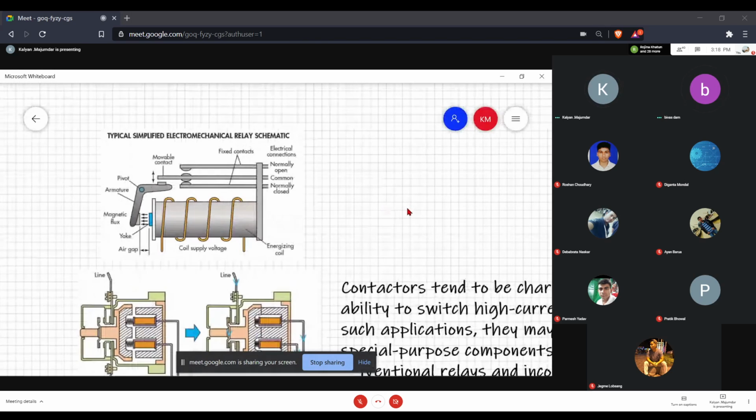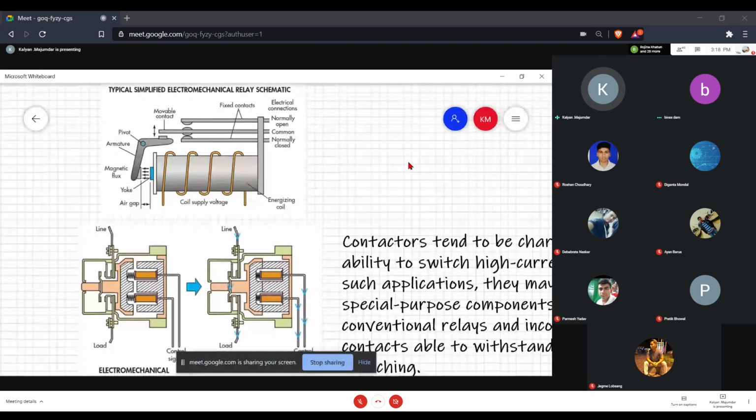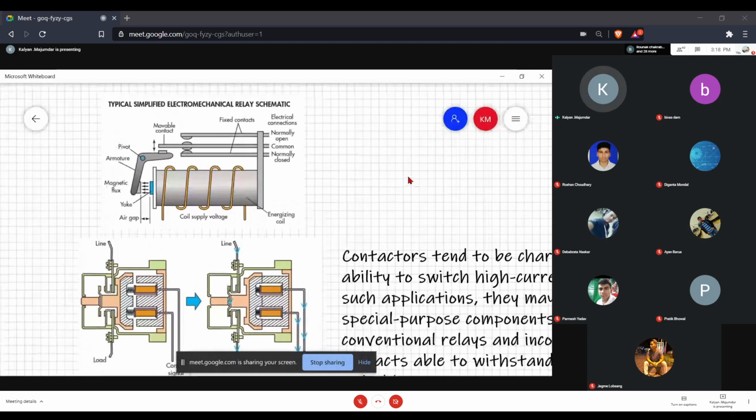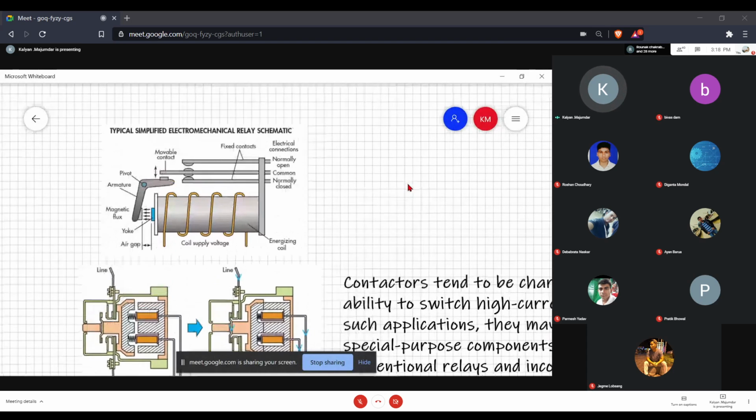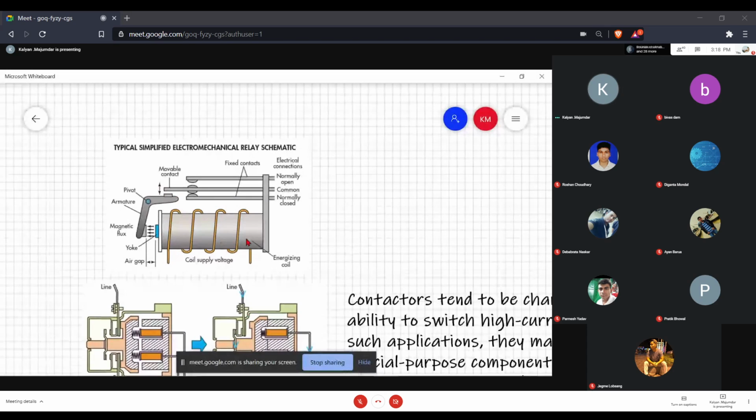Yes, it's visible. Okay, this is what a relay is like when you're constructing a relay. The upper figure is the relay, the lower one is the contactor; forget the contactor part. What have you got? How is it constructed? You can see a coil. Inside the coil, there's a soft iron piece, any magnetic material. Here you have a movable element. This is the pivot. This whole thing can rotate about this.